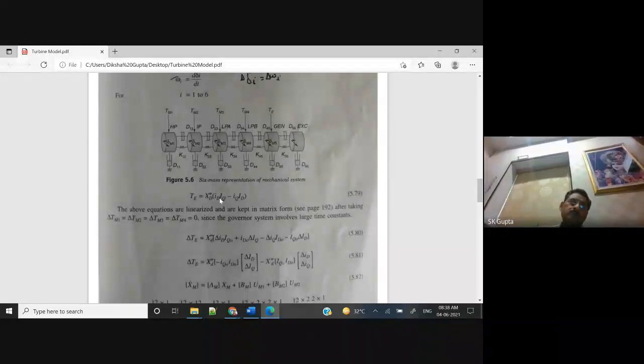But still, when there are two currents from two different sources, then the torque is given by ID in the D axis and IQ in the Q axis. Otherwise, torque is given by, suppose some currents IA, IB and the angle between them, torque is equal to IA, IB and sine of the angle between them. Since D and Q are 90 degrees to each other, sine 90 is equal to 1, and this will be the equation for torque. This equation will be described in detail later also.